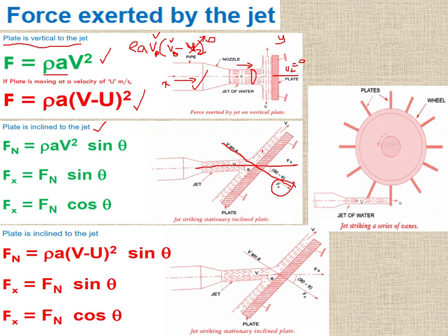So what would be the magnitude of the force? The formula is the same, but the velocity is not 100% perpendicular to the plate. We are only using some component of the velocity which produces force normal to the plate. In the earlier case, the full velocity played a role in producing a force on the plate.